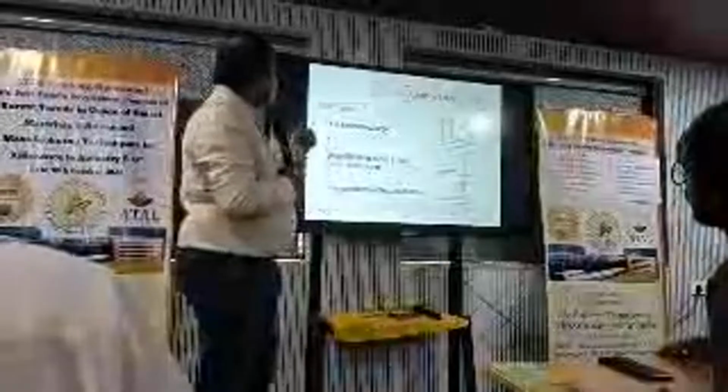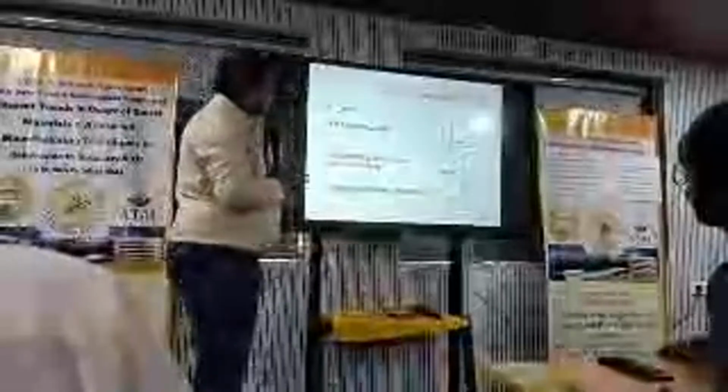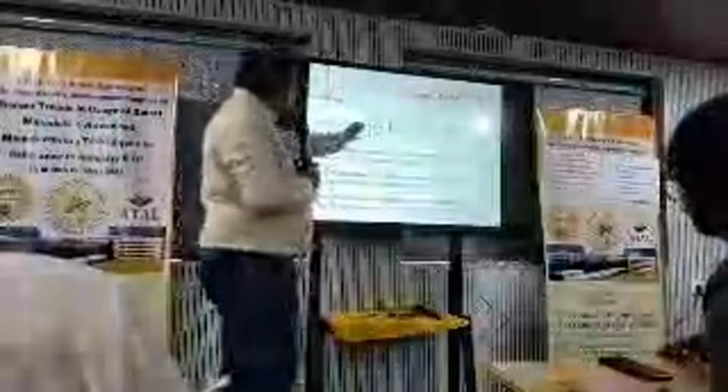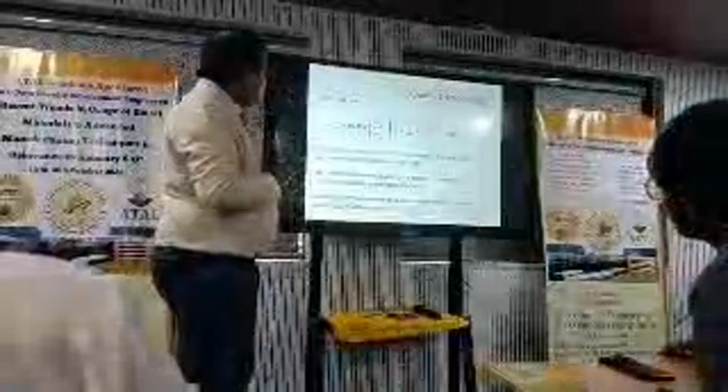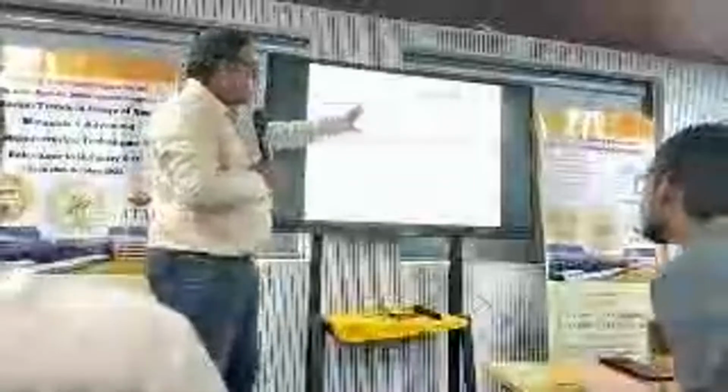The enclosures are freestanding large, freestanding close fitting. This is a close fitting. Depending upon the size, we have to design the enclosures. Again, the insertion loss mainly depends upon the sound power radiated by the enclosure and the corresponding sound pressure. It is a ratio of W1 to W. Finally, the insertion loss should be as high as possible. We have to design the material such that the insertion loss is highest.